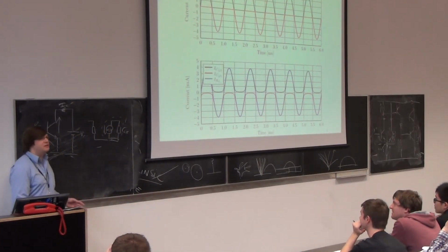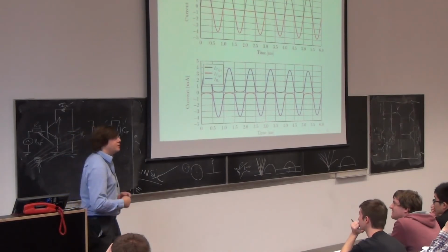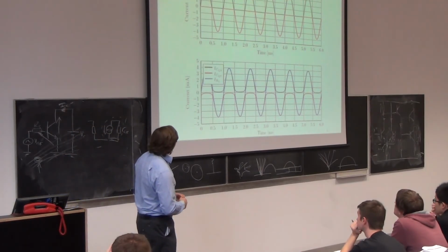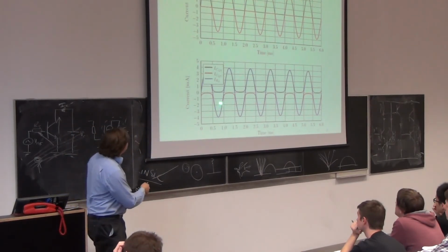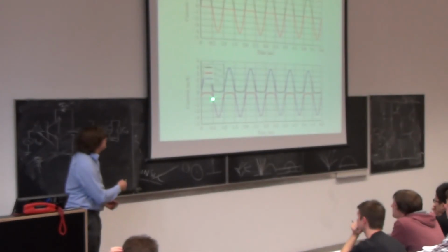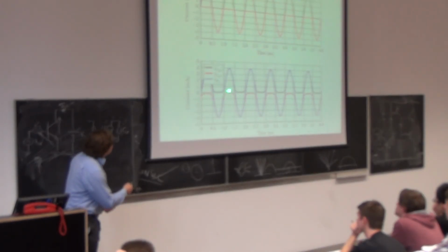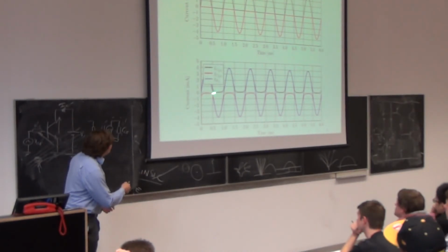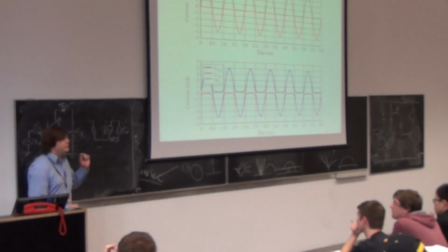I haven't done anything special, I just biased both transistors a little bit more on. If we keep going with this, this is a conduction angle of more than 180 degrees, because I was conducting from about there to about there. That's more than half a cycle. Only a little bit more though.